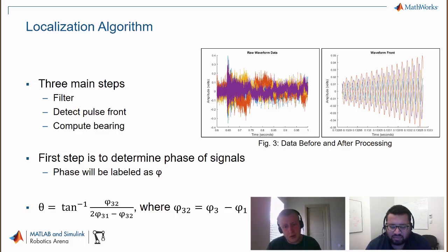Large sound sources in an environment, like motors on your vehicle or anything else producing sound, might need to be filtered in hardware so as to not saturate the sampling of any of those devices, of the FPGAs or of the DACs. So today we're going to show a pure software filter, as the noise in the environment wasn't too loud, and to show something that's a bit more approachable for anyone just starting to work on this problem.